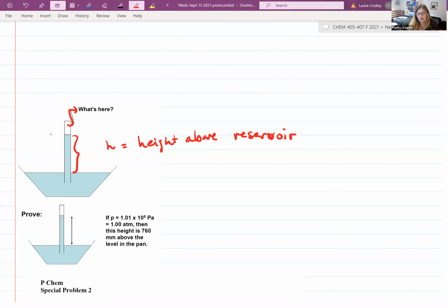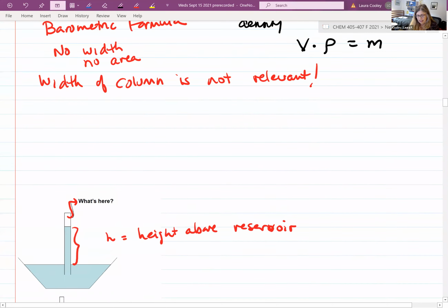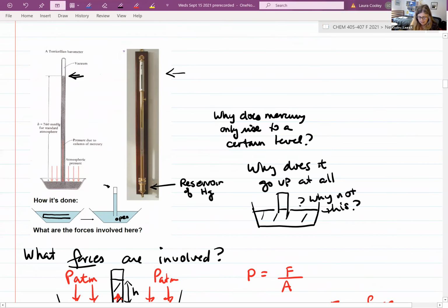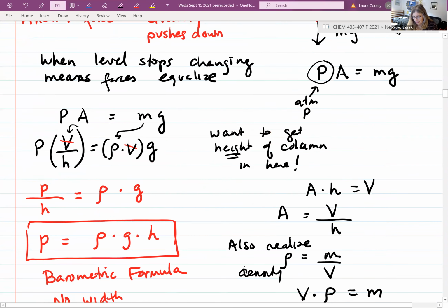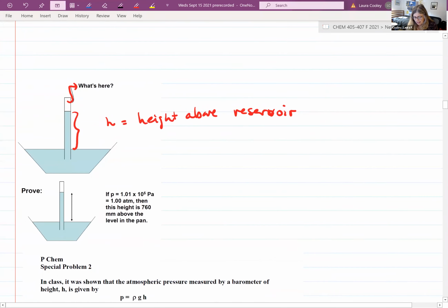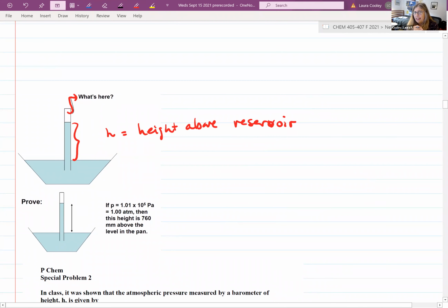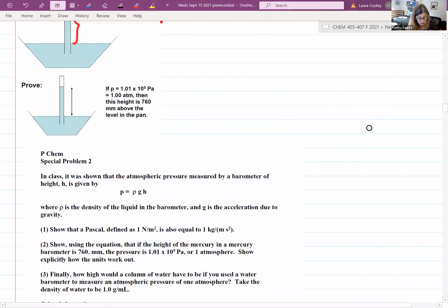So remember, we started with this barometer that was laying flat, right? Starts out laying flat like this, and you raise it up. So basically the mercury is coming down from the top because gravity is pulling it down to an extent. So there's really no air in there. What's in there is probably just mercury vapor. There'll be a certain pressure of mercury above that liquid. So that's really all that's there. That's a very low pressure. So it's almost nothing, but not quite nothing.